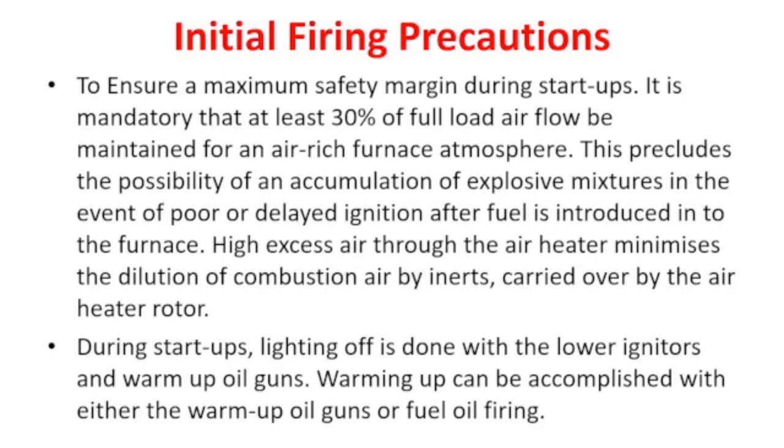Now, initial firing precautions. To ensure maximum safety margin during startups, it is mandatory that at least 30% of full load airflow be maintained for an air-rich furnace atmosphere. This precludes the possibility of an accumulation of explosive mixture in the event of poor or delayed ignition after the fuel is introduced into the furnace. High excess air through the air heater minimizes the dilution of combustion air by inerts carried over by the air heater rotor.